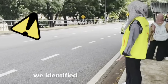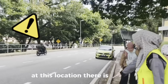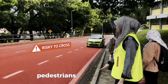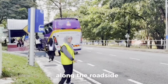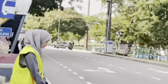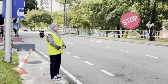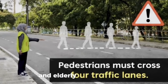Next, we identified an issue related to vulnerable road user infrastructure. At this location, there is a bus stop on the opposite side of the road, but there is no proper pedestrian walkway provided. As a result, pedestrians are forced to walk along the roadside and cross the road without a safe designated path. This situation increases the risk of accidents, especially during peak traffic hours when traffic volume is higher. It also makes it difficult for pedestrians, particularly children and the elderly, to access the bus stop safely.